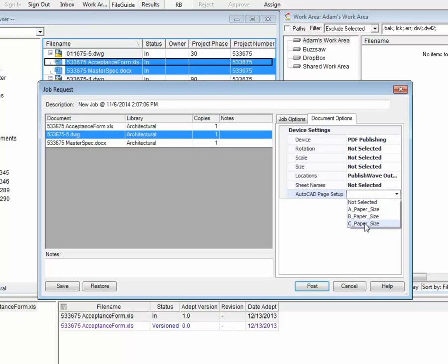It may be for jobs and projects you're doing, but you get to create standard setups where you can decide the pen sizes, the layouts, the fit to page, the extent, even run a script in AutoCAD before those documents are published. So that really opens up a lot of creativity on your part to run AutoCAD scripts before it's published as well. So you can create these for your users, again, to standardize your output. And I will pick page size A as my standard output.